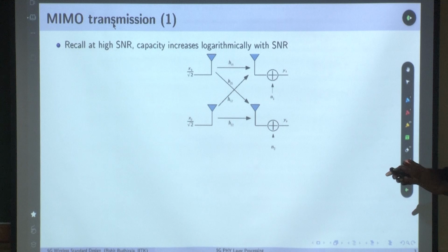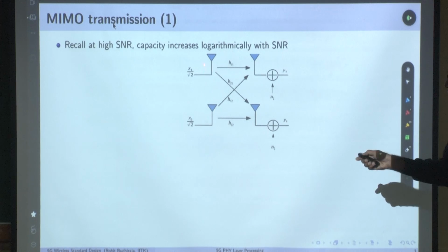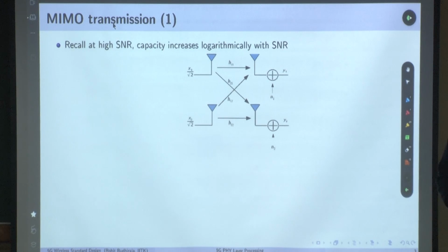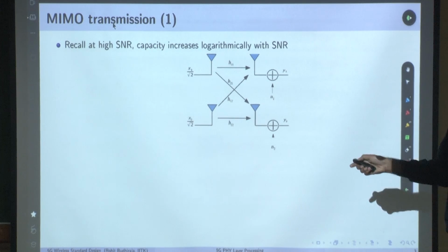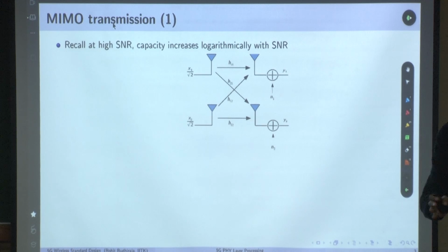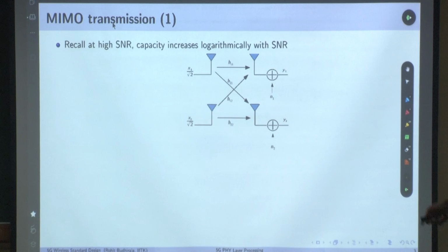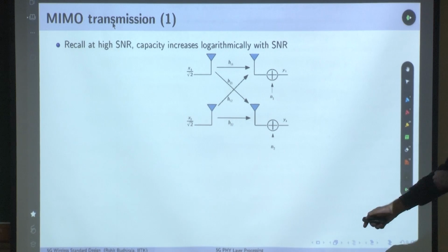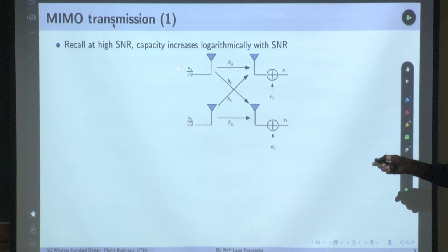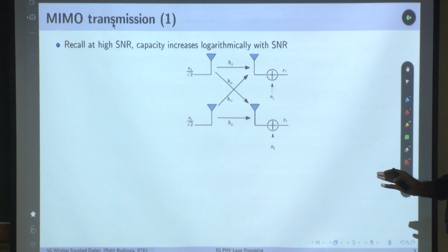But primarily, what are we saying here? What is the signal being transmitted? You see that in this case I am not even precoding the signal. Even though I have two transmit antennas, I am not even precoding the signal. Even then it will give you a lot of gain, and we will see that. So, is the framework clear? I am transmitting x1 by root 2 and x2 by root 2 from two different antennas. If x1 has power p and x2 has power p, what is the total transmit power?